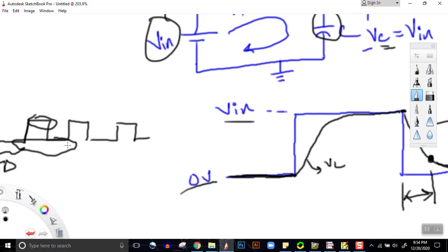That is, the total period of the pulse is from this point to this point, and the time when the pulse will be on is these two points. So this portion, this time over here, is called pulse width or PW, and this time over here is called PER or period.